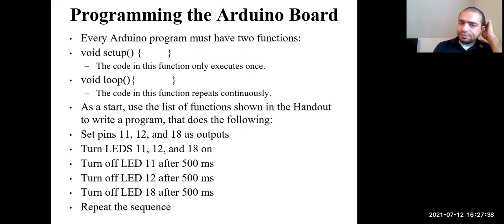So the setup: any code that is written between these two braces inside the setup function only executes once. Now the void loop function, the code in between these two braces repeats continuously.